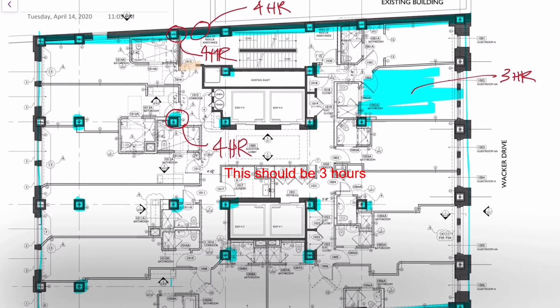And so stair enclosures, elevator enclosures, and stuff that's penetrating the floor like mechanical shafts, these guys that are kind of peppered throughout the floor, probably missing one or two, but basically that's what those are. Anytime we have these penetrations through the floor, that duct will need to be encased in a wall, and those walls will need to be 2-hour fire rated.